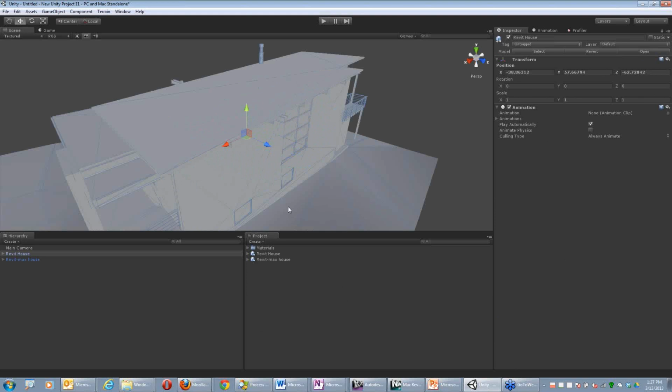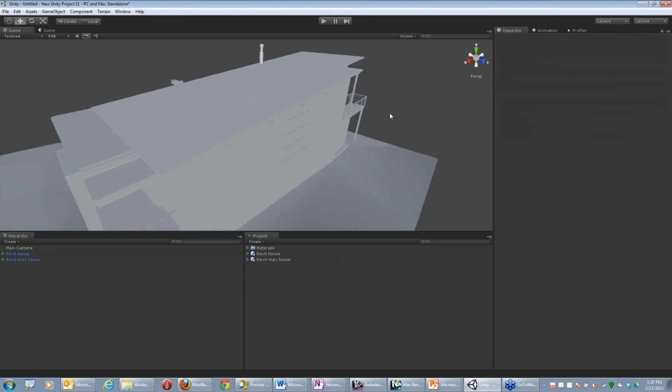If I just want to bring it in, make sure the scale is correct, make sure all the geometry looks good, yeah, I can go straight from Revit in, not a problem. And the nice thing is, because of the way Unity works, I can overwrite existing versions. So if I made changes to the model and I don't want to have to redo everything, it's almost like having a link inside of Revit. I just update the background version, and it maintains all the changes that I've done here. So it really is that easy. Like Leo said, if you download Unity, within a day you can have something that you can start playing around with.